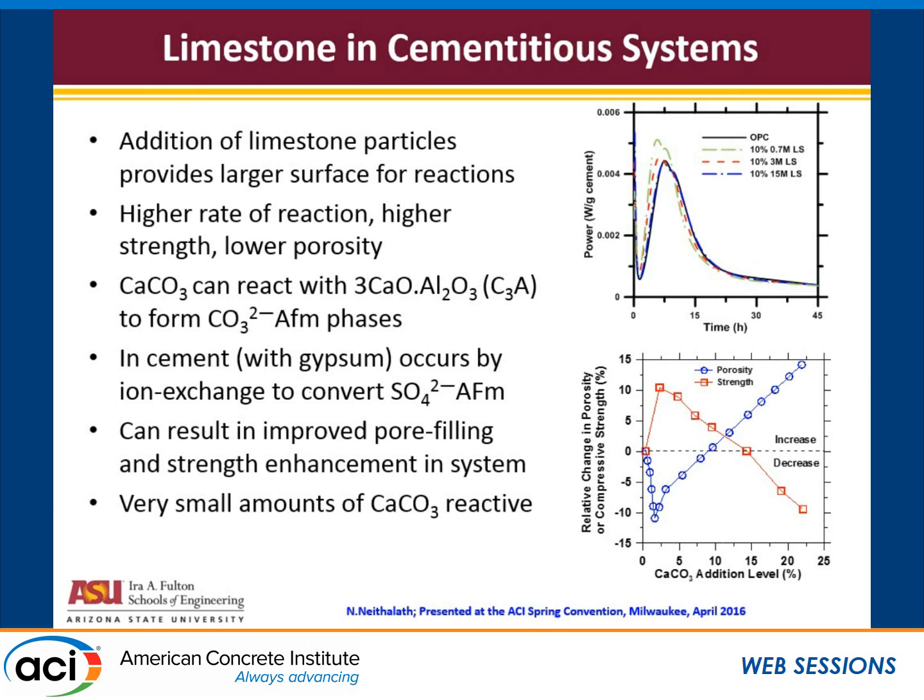Now this can result in improved pore filling and strength enhancements, but a very low amount of calcium carbonate is reactive. If you look at it, at a certain reaction level you have some increase in strength, but increasing the carbonate addition level beyond, typically that number is about 3%, if you're adding only carbonates, anything more than 3%, you really don't have enough of the cement that you took out to do anything with the presence of limestone, so you effectively have reduced strength and increased porosity, which you don't want.